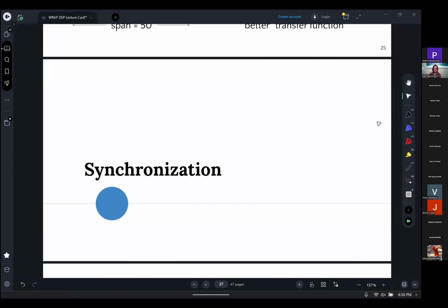Okay, so that was an introduction for digital filtering and how we use it in the RAP system and how you will influence it in this upcoming assignment. The rest of this lecture is dedicated to the problem that I introduced at the end of the previous assignment, which was: how do we handle phase and frequency offsets that might arise during this whole process, when our demodulation requires us to have the same phase and frequency for the sinusoids that we demodulate with?